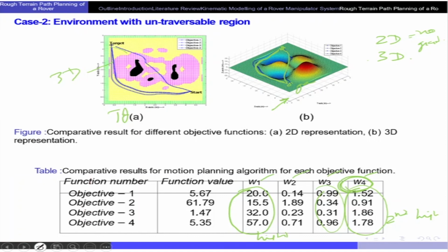the potential field function in 3D. Okay, so we looked at the potential field function in 2D, then we looked at navigation function, then we looked at 3D. Now, something to note is that whatever we have been studying so far, okay, we found a network of paths, we found multiple paths in potential field method. Then we looked at multiple network of paths in, for example, the sampling-based methods, Voronoi diagrams we drew, the visibility graph methods we did. Now we have to answer the question of how do you choose a path now?